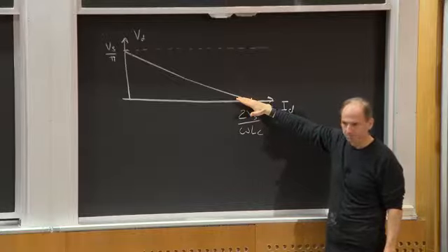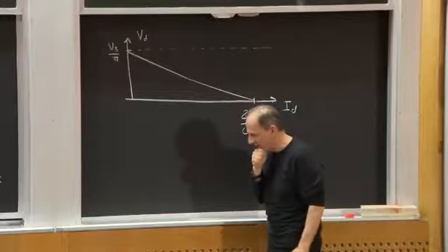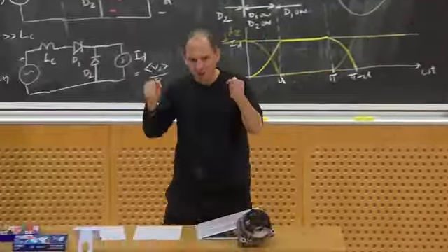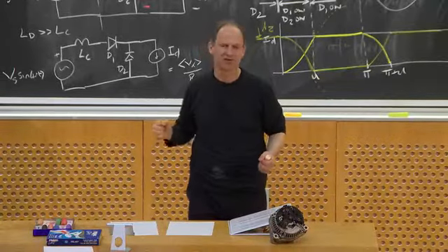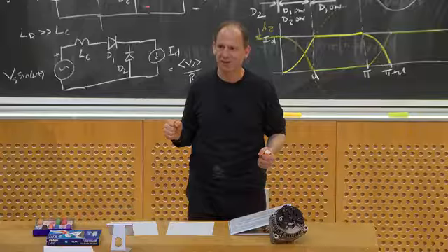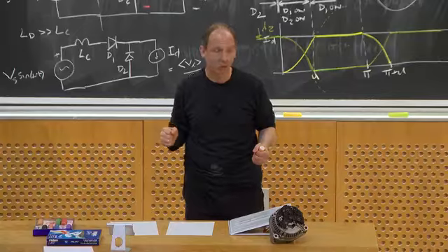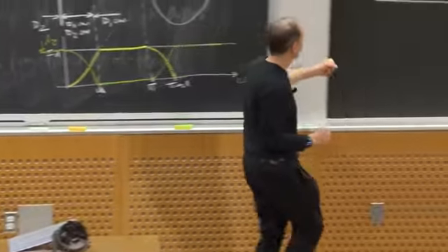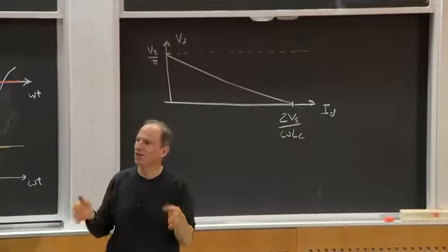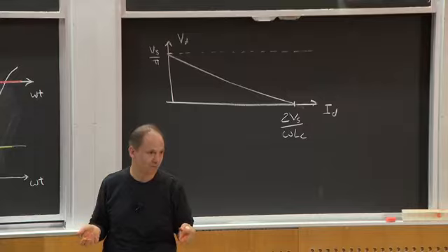Right? And in fact, we once had that. We designed a really high-frequency resonant power converter, and we had rated it for, I don't remember how many it was, like 500 watts or something. And what we found out is we couldn't actually get more than like 400 watts out of the thing. Why? Because the transformer leakage inductance was making it droop just enough that it was stealing our ability to deliver the current we wanted.